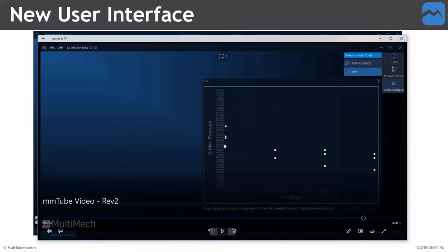When you start gauging the range here, this is significant because a lot of times with finite element analysis, you build a model and you run it over and over again, you're going to get the same result every time, with the same boundary conditions and the same assumptions used. In this case, we're now bringing stochastics into the equation. We're trying to get a range of burst pressures for these different tubes.